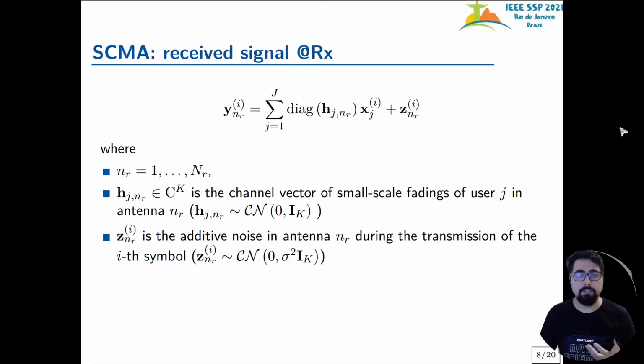affected by each fading channel. Since we consider multiple receive antennas, there are NR copies of the signal, with different fading channels. We assume Rayleigh fading channels constant during all the channel uses necessary to receive all the packets of one coded message. Later we'll drop the package index I and focus on the SCMA detection algorithms. Additive white Gaussian noise is also present.